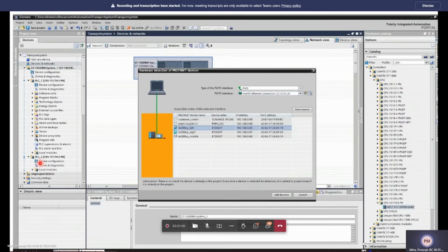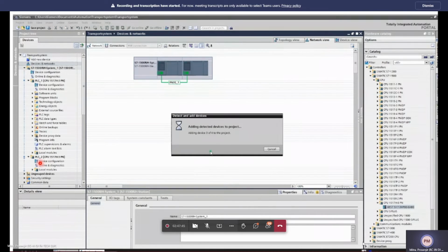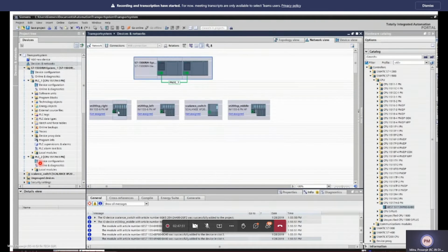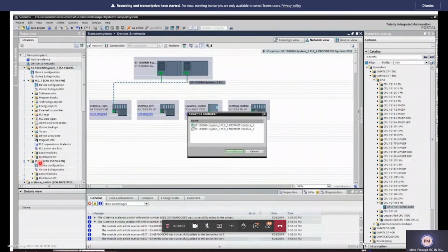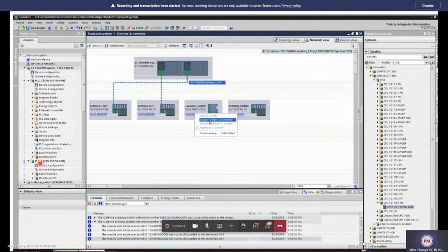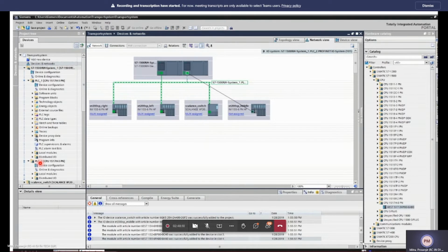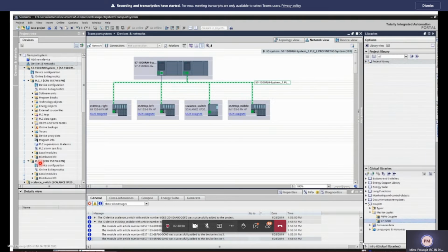So once you detect all the different hardware which is required, you can just select it, and all the devices will appear. And individually connecting the devices is very easy. You can drag and drop to each and every CPU, and you will see here there is a multi-assign option appearing. Another option is selecting directly and double clicking and selecting those particular CPUs. You will get a multi-assignment also, or individually drag and drop. So both options are there, and you can see all the CPUs are appearing here.